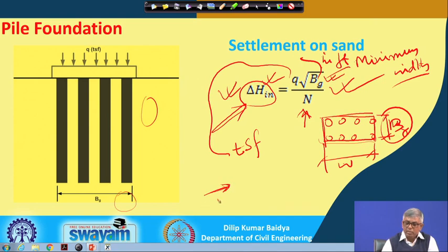So that means we now have three different models. One is pile embedded in uniform compressible soil. In that case we have to consider the equivalent raft at 2/3 length of the pile, and then the rest of the calculation, like what is the delta sigma and what is the effective vertical stress before applying load, and then based on that one can find the consolidation settlement.